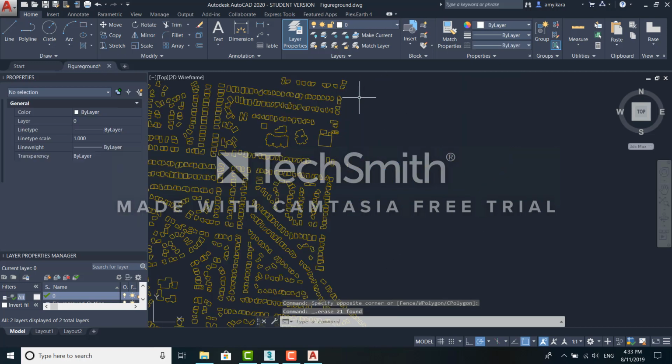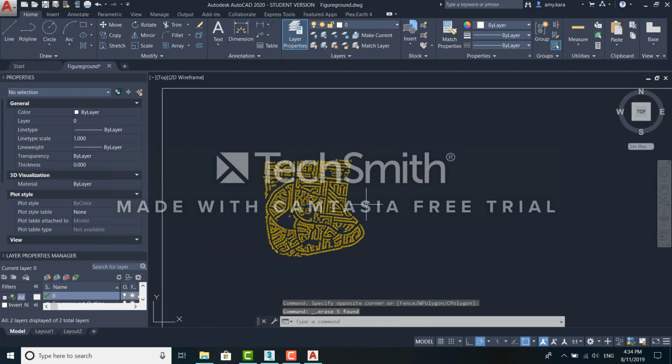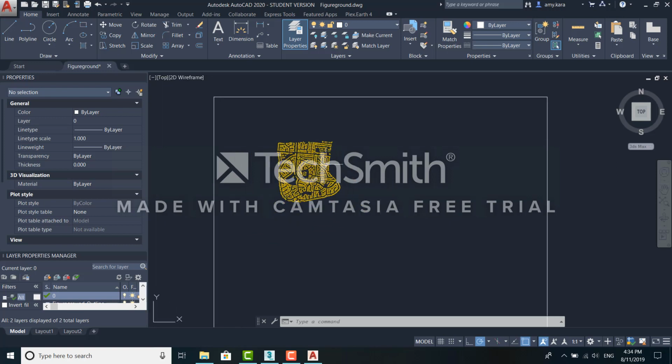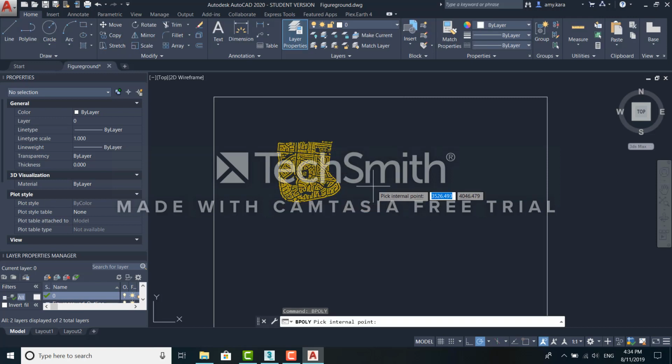This will also probably be more successful, as I may have not actually gone and deleted all of those extra non-enclosed polylines. So here I'm actually just going to show you 2 quick ways in which you can do this now that we've just got a smaller section. The first is to type in bpoly and press enter. And then we're just going to go OK, and we're just going to select inside our rectangle.